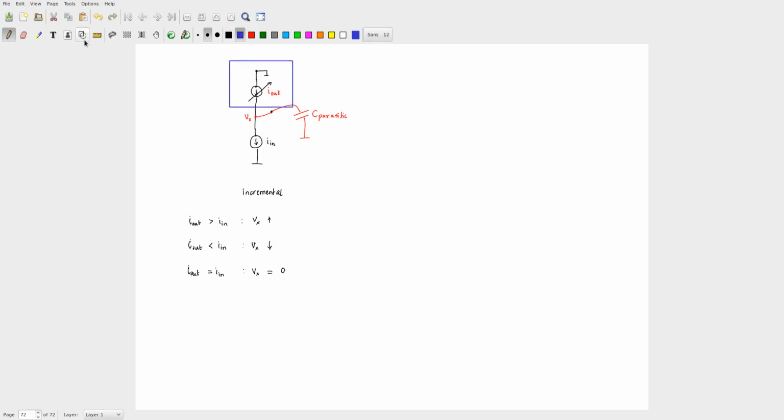The blue box is going to become the MOSFET. So, how will you draw it? If it's the MOSFET, and we are looking at the incremental circuit, this is essentially going to be that voltage controlled current source element. You are going to have this thing like this. This will be some gm times vgs.